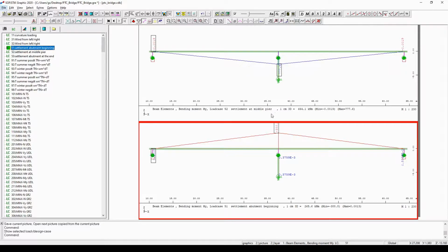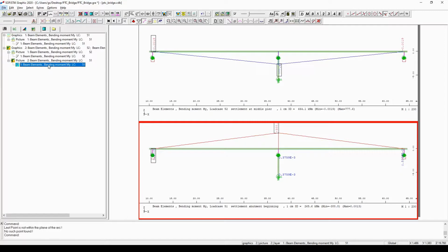However, there is a slight inconvenience at the representation of the values, because the magnitude of the diagram is a bit too big, and also maybe the text height is a little bit too big. So now I will try to change this and apply the change settings to the first picture as well. The way how you can do that is to go back to the Layers tab. In the Layers tab, of course, you need to select the layer you would like to change. So here I would like to change the amplitude of the diagram a little bit, and then I do not need to even change the text size. This is going to be fine for me.